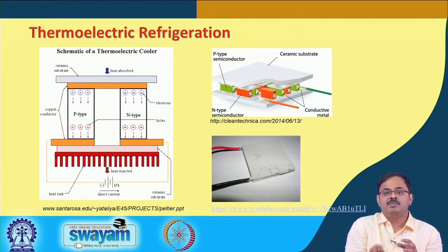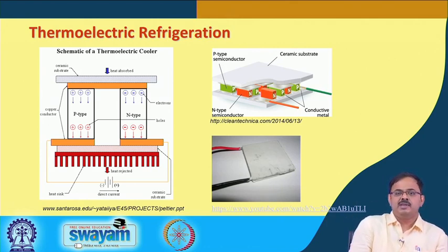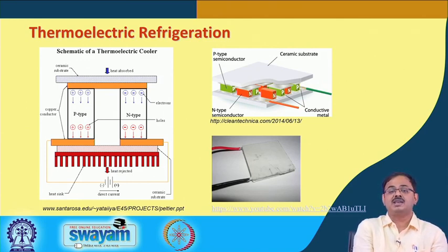Can you put some of these thermoelectric coolers at the exhaust pipe? Because on the inside surface of that pipe you have very hot gases at 600-700 degrees C coming out. The other side is probably more than ambient, but probably within 100 degrees or so. So, there is a large temperature difference, and that can be leveraged using this thermoelectric effect to generate electric power.